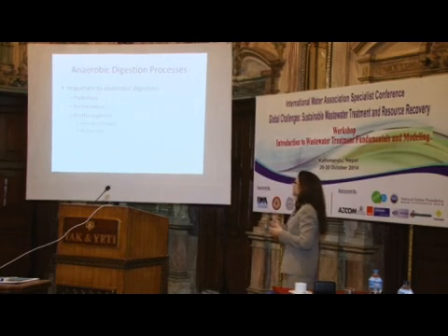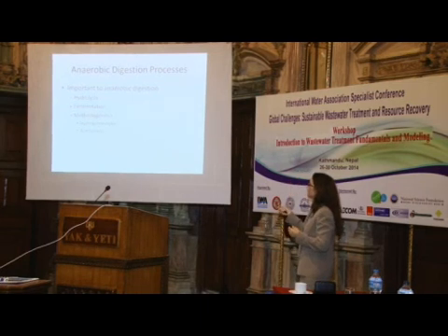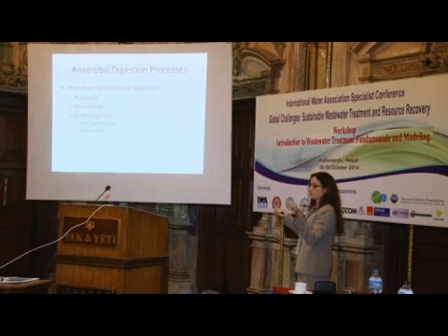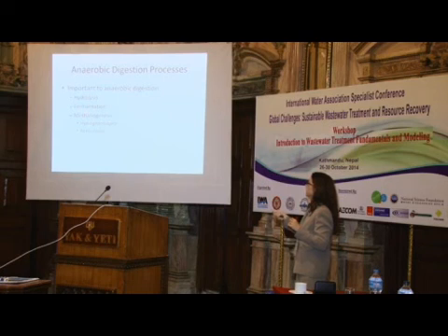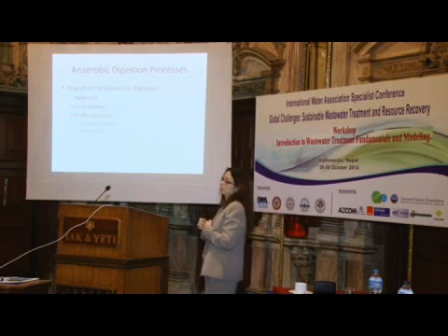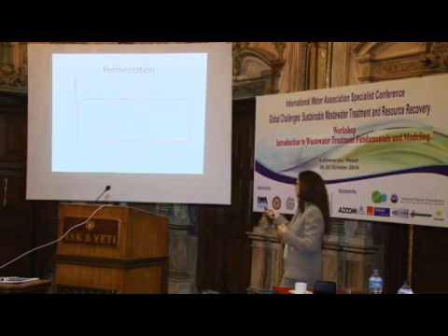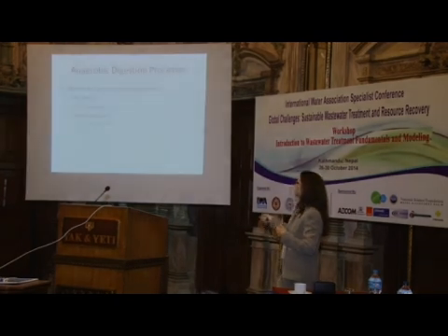So again, in anaerobic digestion, our critical processes are the hydrolysis, because we have these large molecules to break up. Once they're broken up, fermentation, methanogenesis, and then we have 2 different kinds of methanogenesis. We have hydrogenotrophic and we have acetoclastic. So what I'll do is I'll go through each of these in some detail.